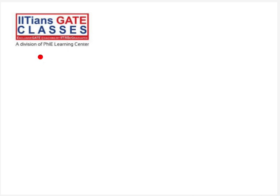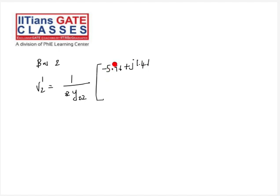Then we go to bus 2. For bus 2 we can calculate V2 dash 1. V2 dash 1 is 1 by Y22, which we can calculate from this, then minus 5.96 plus j1.46. So why does this sign change? Because this is a load, so the effective power injection would be negative.